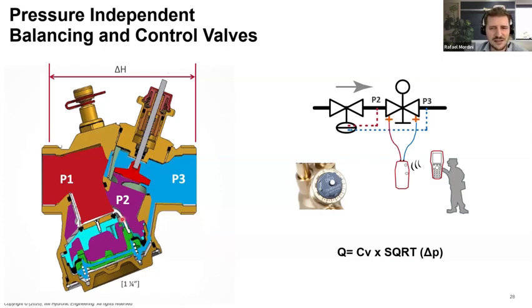That's some smart valves like the Belimo Energy Valve or IMI TA Smart. Those valves have flow sensors installed inside them, ultrasonic or magnetic sensors, doesn't matter. What matters is they are measuring the flow rates, and they know when they overflow in any circumstance. Oh, I am halfway closed, I should have just 20% of the flow rate, but I have 30. The valve does its own correction. But that's the only way for you to have a control system balancing the system for you.